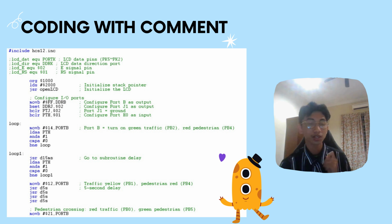Moving on to the main traffic light sequence, the code before pressing the push button is included. Before pressing the button, port B is set so that the traffic light for the road is green and the light for the pedestrian is red. Next, the code for when the push button is pressed is also included, as well as what happens after it has been pressed.